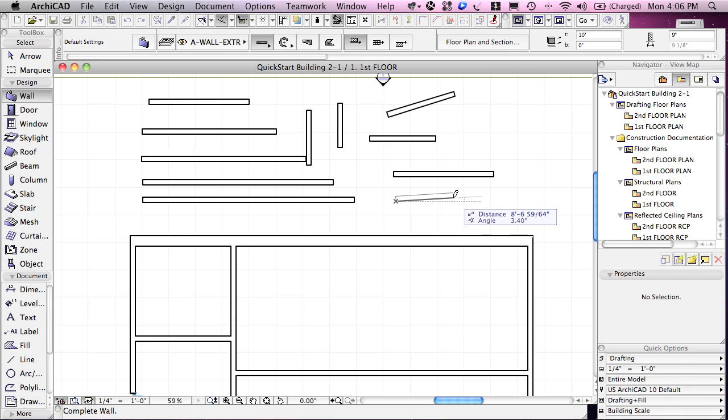And you can, for example, press the Shift key down and it'll jump to that angle, and then you can point at something else and line it up. So this is a quick way to line something up. Press the Shift key down while it's in the right direction, and then while the Shift key is held down, click when the cursor is lining things up there.